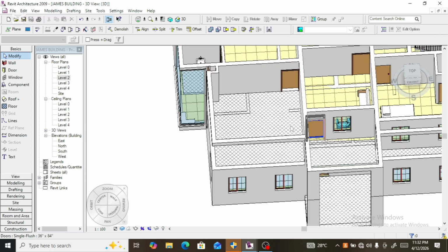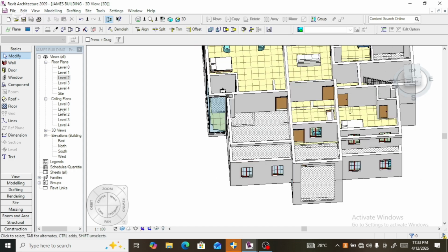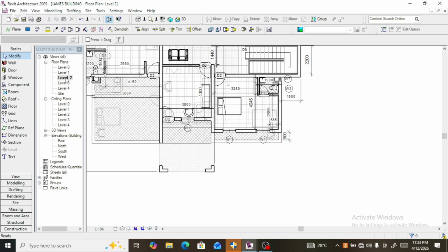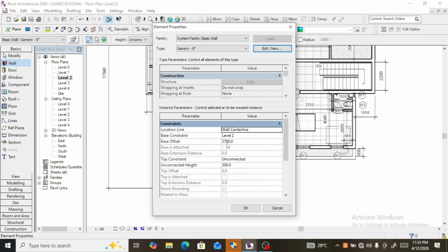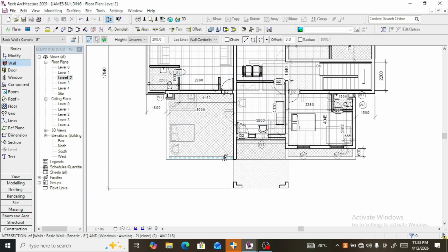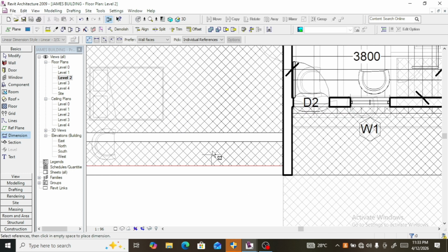Therefore, something is supposed to be done downstairs, 600 span for that flower pot section. So let's do that quickly on this level. Let's say our wall is supposed to be 200. It's supposed to offset from 0. Set it from here. Go there. It's aligning already. Highlight. Dash it in. Finish. Remove the tool. Check our measurement if it's corresponding.